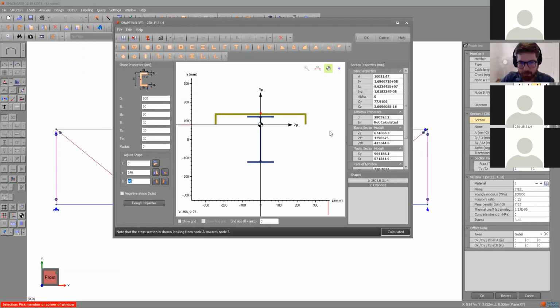So the more complex a parametric tool that you're relying on, the more potential there is for there to be mistakes within that, and the more careful you should be in error checking with manual calculation if it's something that might play a significant aspect in the overall structural performance.